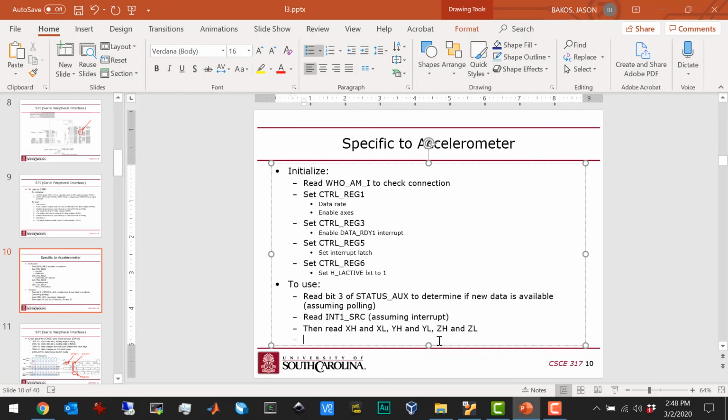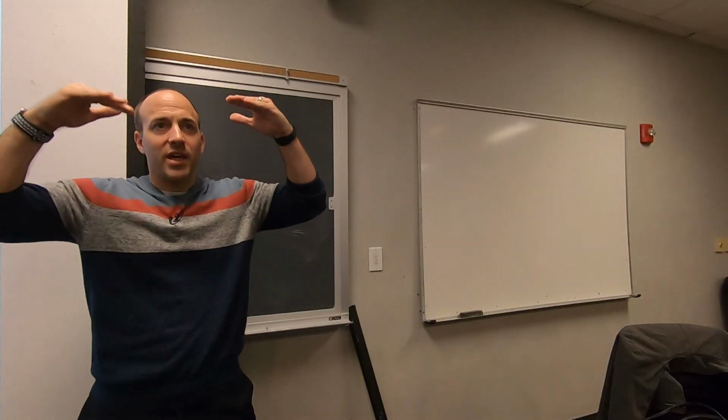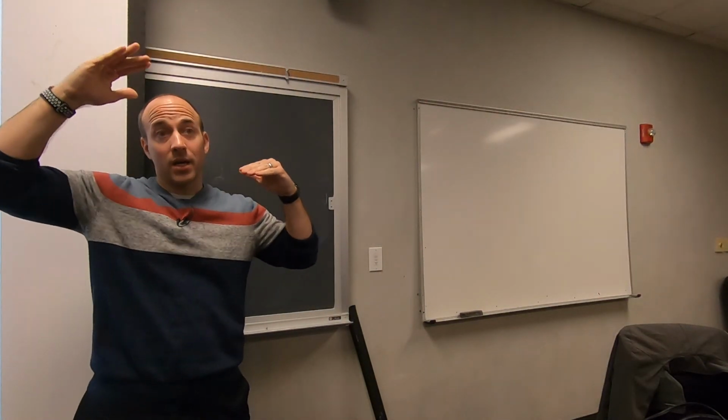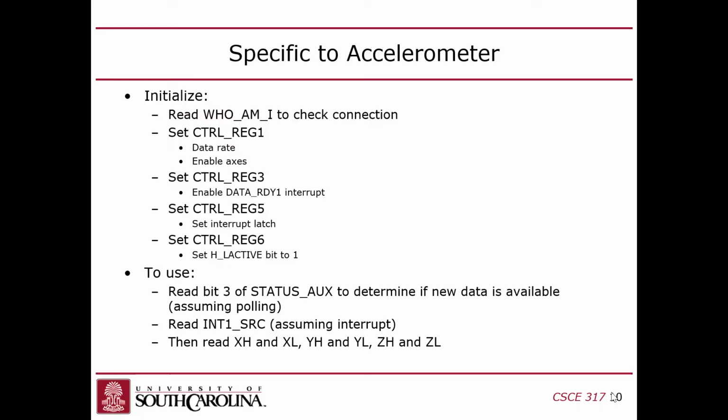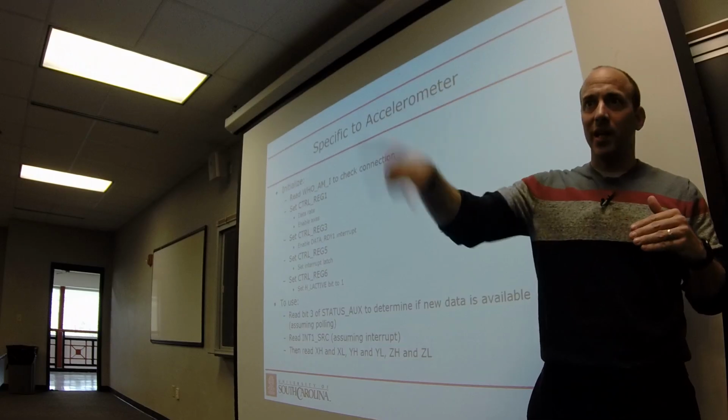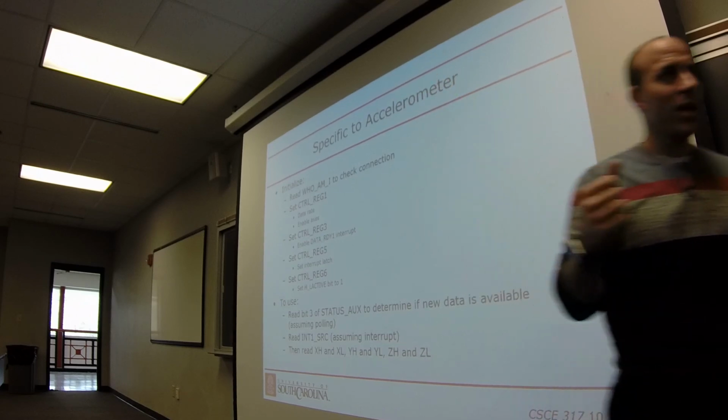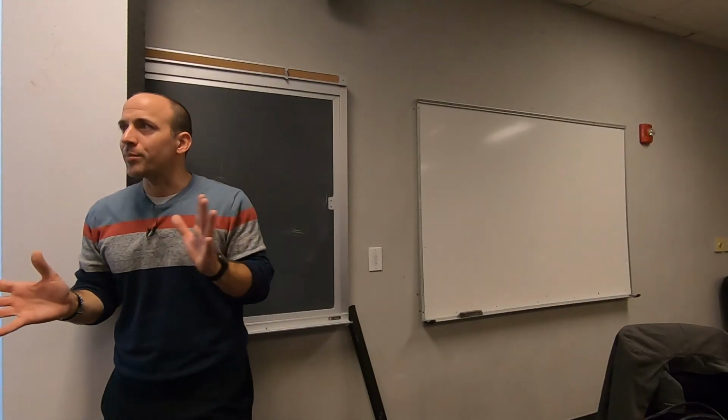So that should make the interrupt pin go high, right? So it'll acknowledge the interrupt. Otherwise, if you don't do that, the interrupt pin will still be pulled down, and so once you return from the interrupt handler, you're immediately going to go back into it again, right? You need a way to acknowledge the interrupt.